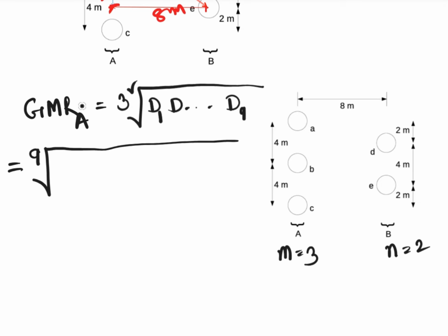And now for the distances, how many distances? First of all these 3 equal conductors, for that individual strand distance for R1 or R prime is equal to e to the power minus 1 by 4 times the radius R, and R is 2.5 millimeter.